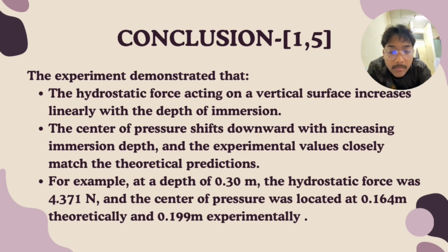For example, at a depth of 0.3 meter, the hydrostatic force was 4.371 Newton, and the center of pressure was located at 0.164 meter theoretically and 0.199 meter experimentally.